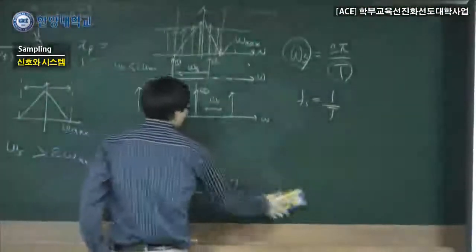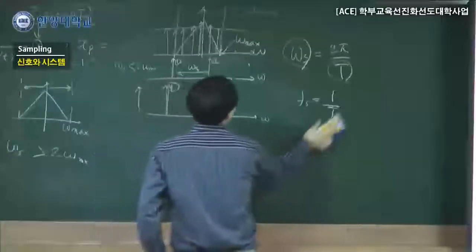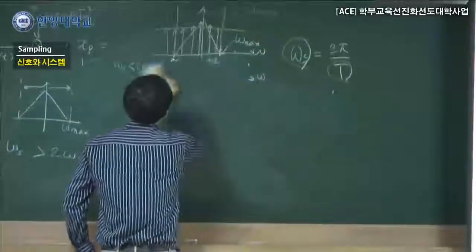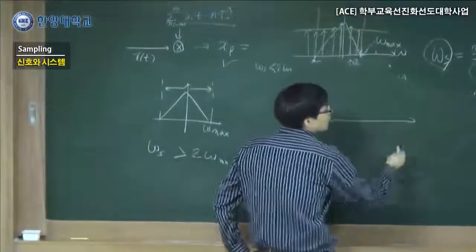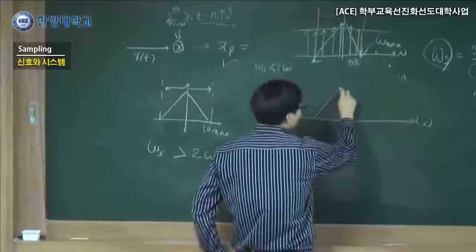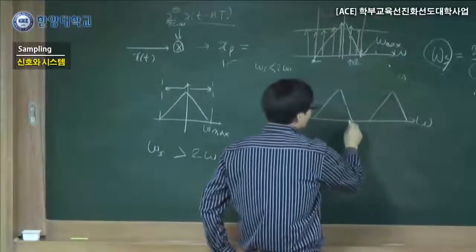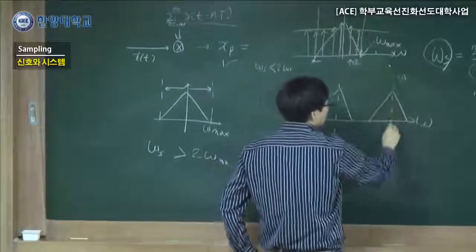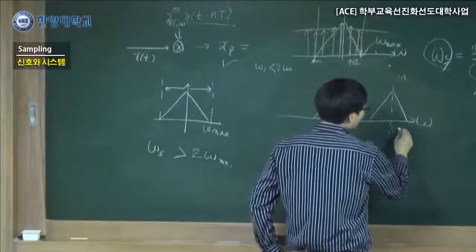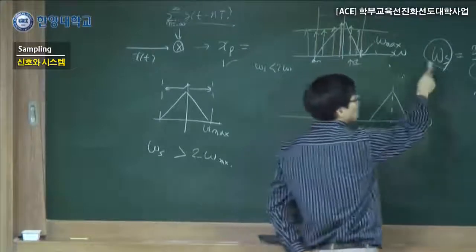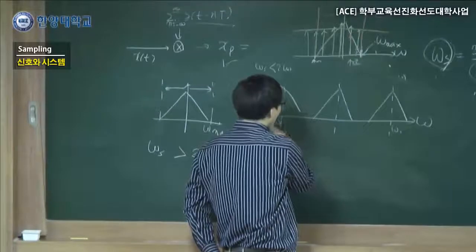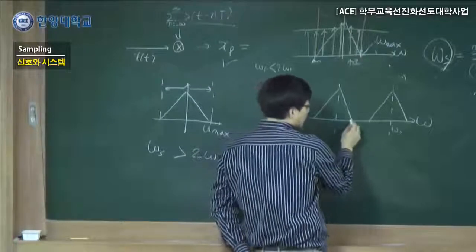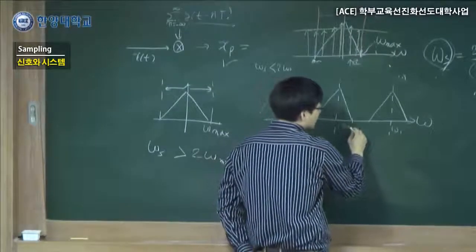We can also think in the way of the result of the transform. So in the case of the discrete time Fourier transform, when you have it, they are periodic. Now we are doing it with omega s, which is the sampling frequency, so their period in frequency is omega s. This is their max.